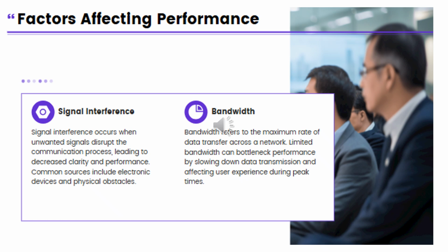It has the capability to reduce signal quality and lower data throughput. There may be drops in connections, and of course security concerns. Proper interference management is essential for network reliability and performance. Techniques like frequency planning, spectrum analysis, and dynamic channel allocation help to minimize this interference.